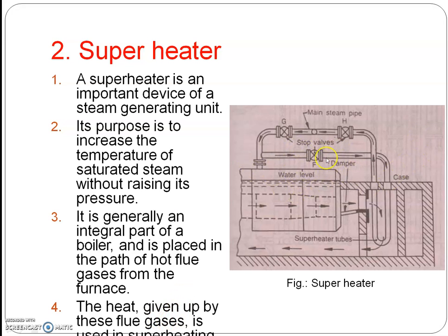The superheater is very essential to increase the efficiency of the boiler. In the schematic view of the superheater, the steam is recirculated through the superheater region by radiant heating and convective heating. The radiant heating section is a heat exchanger using the flue gases to produce the superheated steam. The saturated steam is converted to superheated steam, which can easily rotate the prime mover at high efficiency.